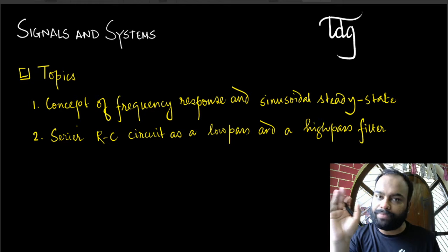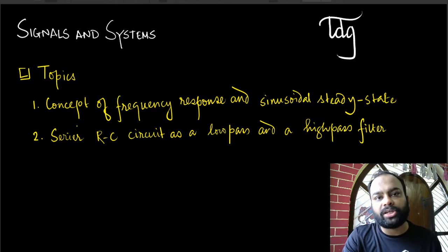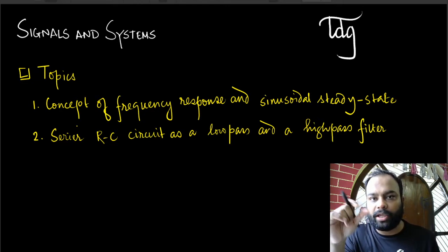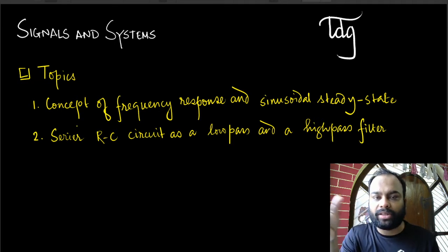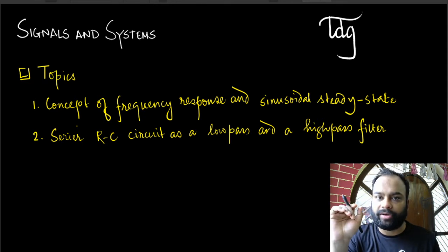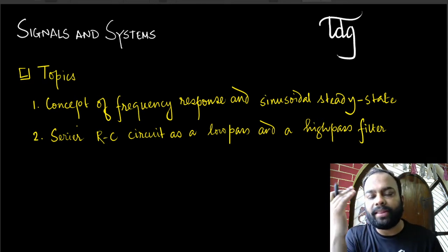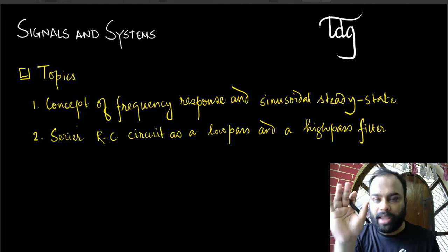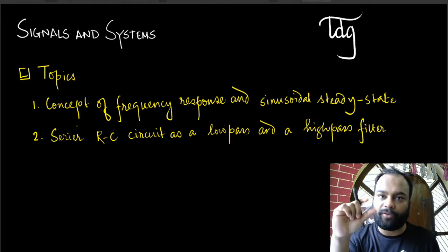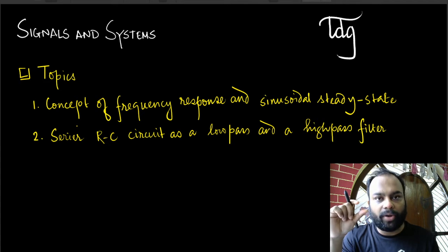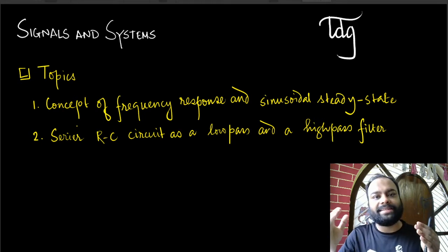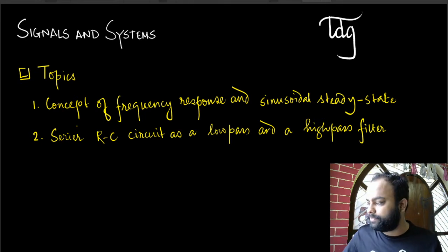So that is something you know, right? And you do these calculations through phasors, right? You apply phasors, you multiply their amplitudes and add or subtract their phase angles, right? You do this kind of computation, right? But today we are going to see where this computation actually comes from, and that computation is not just applicable for electrical circuits. That kind of computation is actually applicable for any linear time invariant system, namely an LTI system in short. For any LTI system, this kind of discussion is actually valid.